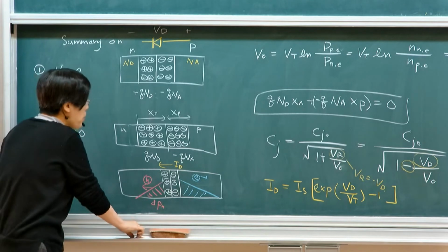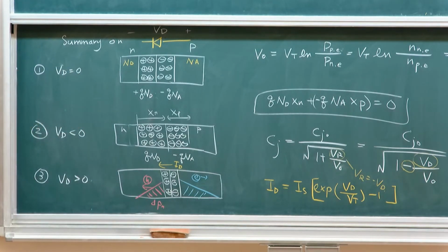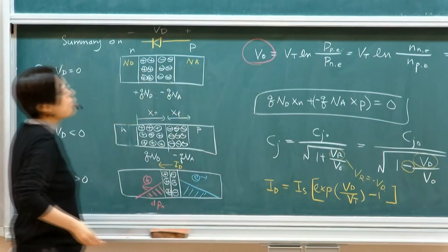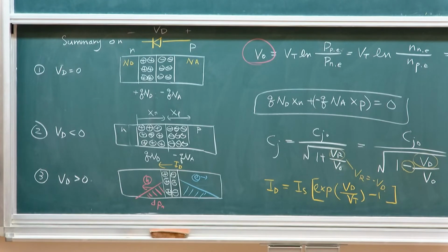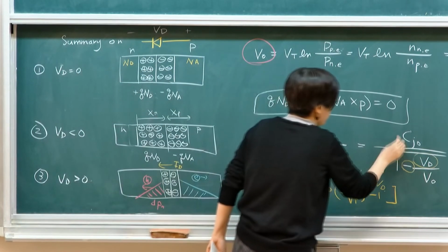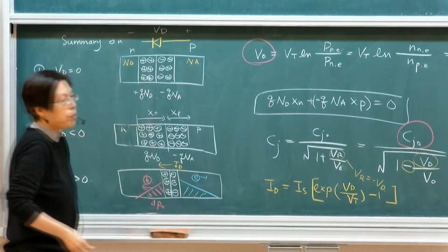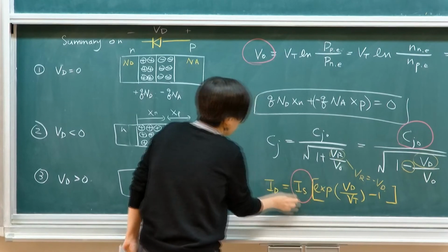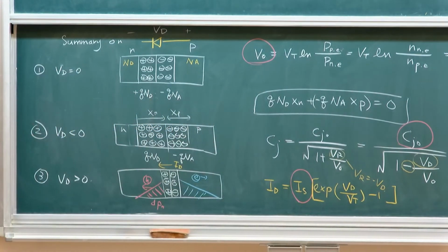So in a PN junction, what are its key parameters? One is, let me highlight, the built-in potential, which is given once these doping concentrations are fixed. And then CJ0 is typically a device parameter that will be given to you. And then finally, the reverse bias saturation current. So these are the parameters that will typically be given to you in a device model file.